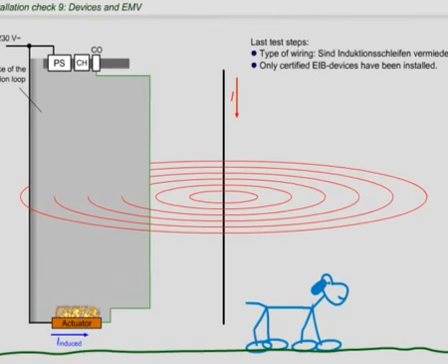But what has this abandoned dog to do with our check? It's very simple. The EIB KNX installation should not be equipped with devices that are not programmed. If an additional line coupler is necessary for a later expansion of the bus, it must be programmed together with all the other devices of the system according to its special requirements.